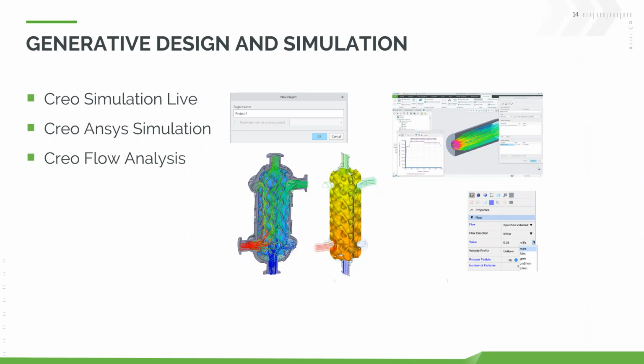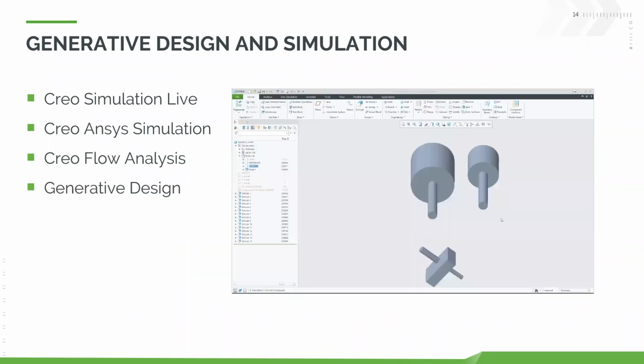Also behavior modeling integration. If you haven't worked with that before, that's a Creo parametric modeling tool that we have for automatically solving different parameters that you lay out given for a specific goal that you want to solve for. And now this works in our flow analysis studies as well. For example, if you wanted to solve for an exit velocity based on these 3 or 4 parameters, we just let the system go run and find it, see exactly what affects it, and we can do an optimization to solve for whatever particular goal that you lay out. That could all be done now within your flow analysis.